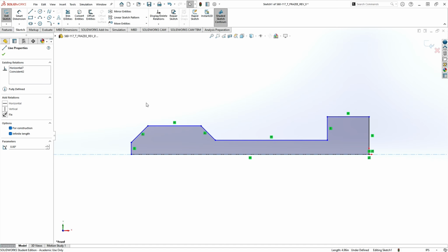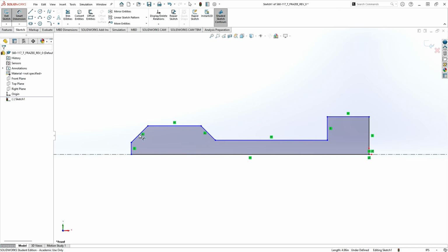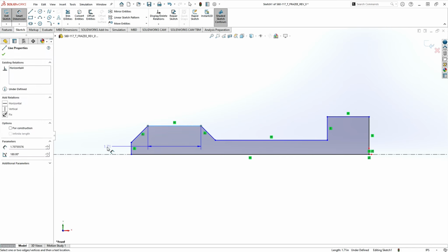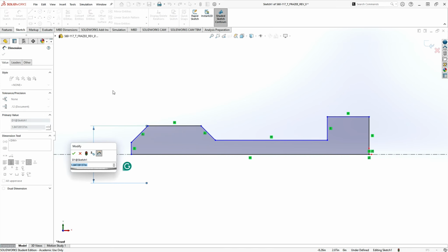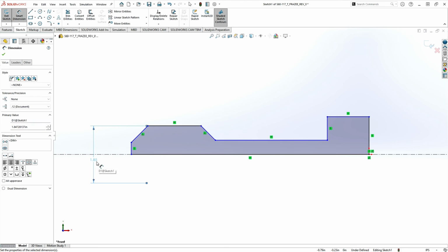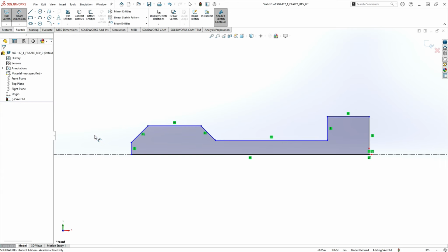If you're trying to fit the screen, the hotkey F on your keyboard will center the screen. Now, I drew this at some arbitrary scale, so we're not sure what's going to happen, and you may have different results, but you can always hit undo and try a different approach. If we're dramatically different than what our finished part is, then we could have this thing go way out of scale. Okay, so it is quite a bit out of scale. So that's going to reverse my chamfers. Let's go ahead and delete that dimension, and that was probably a poor choice.